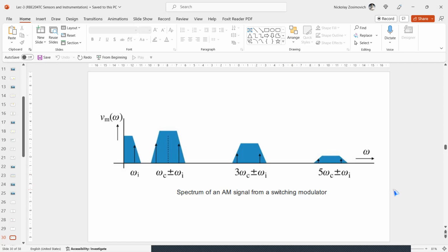What does this mean? It means basically offset, drift, and low frequency noise can all be kept far from the new signal frequency band. And when very low voltages must be measured, it is recommended to modulate the signal prior to any other analog signal processing that might introduce DC error.